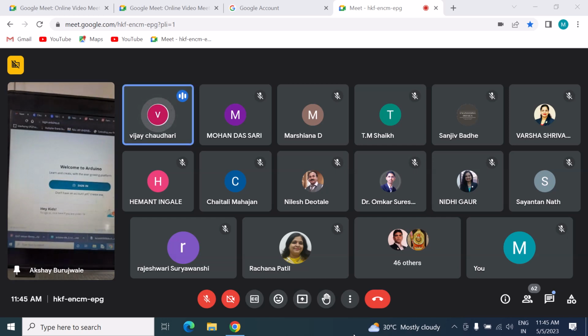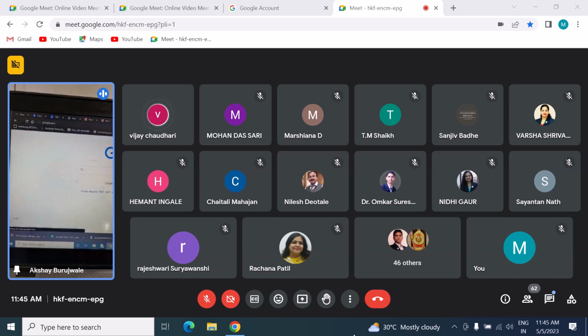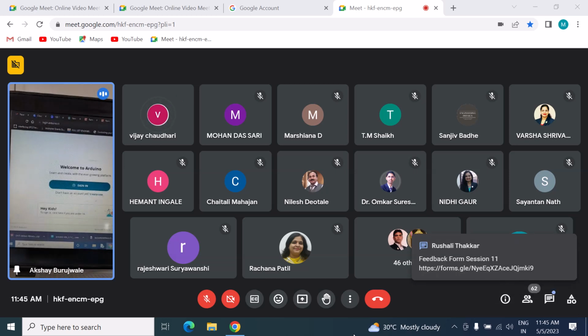I would like to know about LoRa that we have seen. Okay. ESP LoRa is a long range connecting module. That means it is a long distance communication module. We are using ESP8266 for the Wi-Fi connection. It is in a limited range, based on a BLE basis, like 5 to 6 meters, 10 meters, 15 meters. It has a maximum range. But if we have to go for rural kinds of applications where the network is not available, in that case we can use LoRa because it has long range communication. In a rural area, it goes for a maximum of 12 kilometers of range.